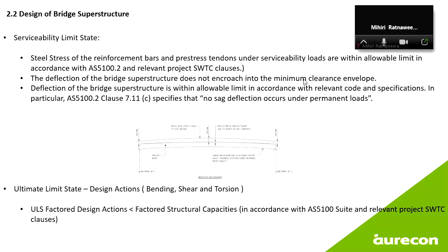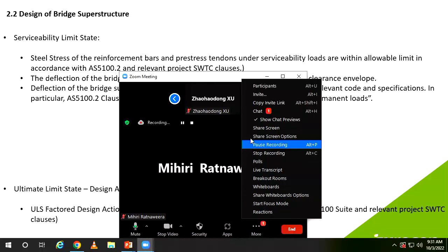When you have a live load going on, your bridge starts to deform. That deformation can never encroach onto the train, otherwise they will be touching each other. The serviceability limit state design also talks about the crack control requirement for a typical reinforced concrete, which means that the durability and performance of your bridge can last for the design life that your client really wants. For example, AS5100 specifies 100 years, and then some of the clients are asking for 120 years design life now.